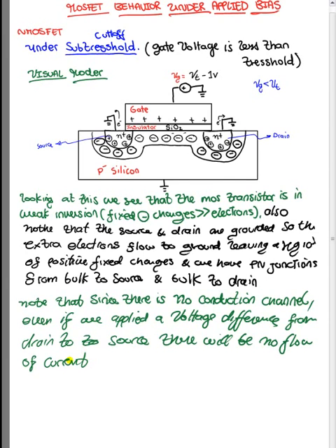In reality, there is a very small quantity. If you apply a very high voltage from drain to source, you still have a few carriers here, right? And due to the high electric field, if any of them gets in there, it's going to go. So it's going to be a very small current, if any. Except nowadays they are using some of these devices in sub-threshold for minimization of power consumption.